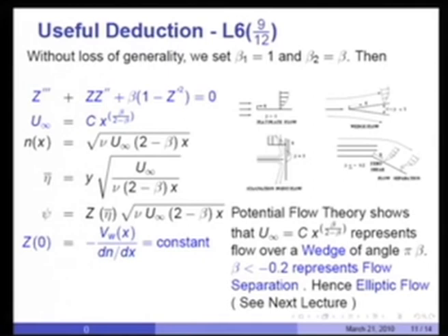And I will have what is called a stagnation point flow, because the flow would hit a plate perpendicular to it and would tend to go this way as well as this way, and in the positive x direction the velocity profiles would be like as shown here. But I can also have negative values of beta, and that is what is shown here.